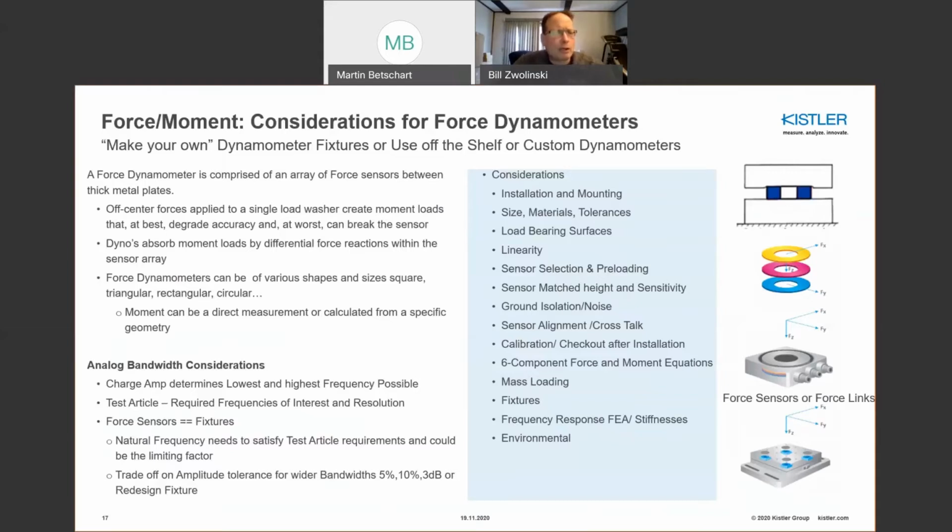So now we want to go into force measurement, and we're going to spend a few minutes on this. So I talked previously about a force dynamometer, and what I want to say first is that a given sensor that you might see, a force sensor, is very much optimized for measuring axial loads, okay? So axial loads would be anything, say, going through the center of the sensor, for example. In a lot of hydrodynamics applications, you're not faced with such axial forces. It could be a model of significant size. It could be a structure of significant size. And now it's not so easy to identify, say, an axial force.